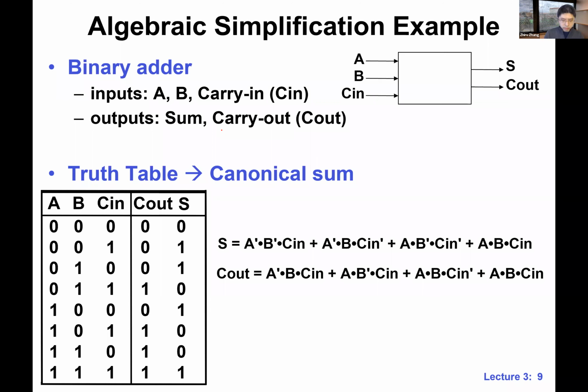This is a truth table that you have seen in the first lecture. I just want to convince you again that this is indeed doing addition. Let's just focus on this last row. We are adding up 3 ones, so we are supposed to see a 3 as a decimal number. But since we are doing binary logic, a binary circuit, everything is in 0, 1. If you look at the final output, there's a 2-bit output, and we indeed get 1, 1, which is a 3. So we are doing addition here. You can also check out the rest of the rows.